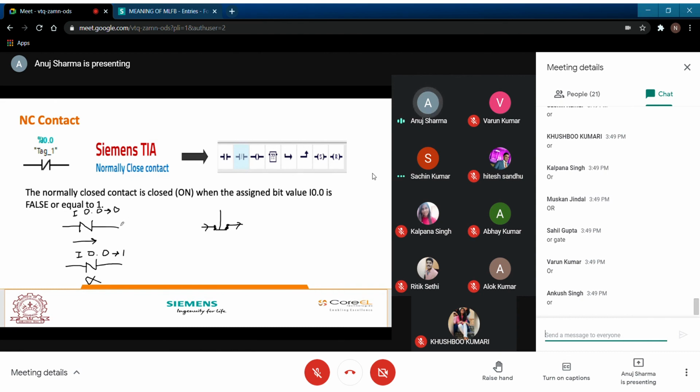So your Q0.0 will be 1 at this point of time when I0.0 is 0, and your Q0.0 will be 0 when I0.0 is 1. Understood?